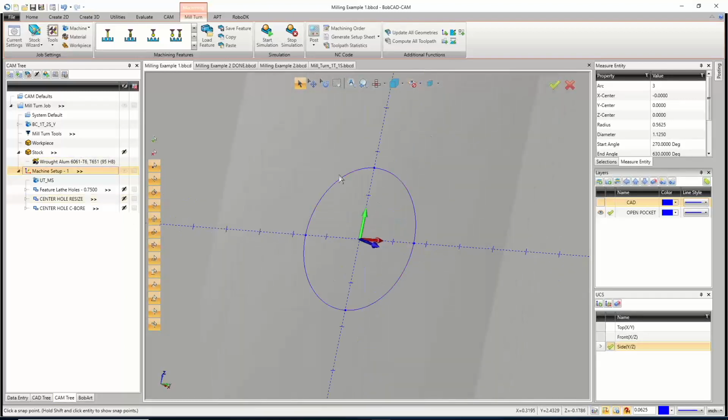And to pick the points real quick and easy, I like to use the selection mask here on the left. Yours might be down at the bottom or even on the right. But if we click this no mask button right here, it turns off all the selections. So if I drag a box, nothing happens. If I turn on that point mask, and I drag a box, it picks just the points, which I can then delete.